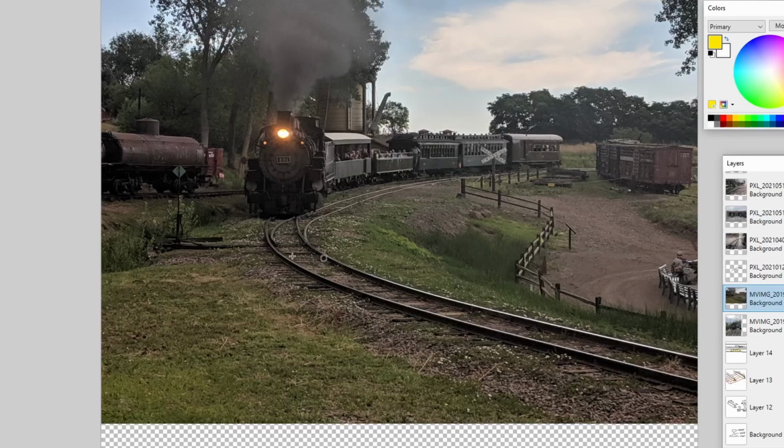Equally important to that is proper grading and proper drainage. Because another problem that we faced here at this location was that the water was kind of pooling and collecting, and wet ground likes to move, and that does not help us run trains. And so we actually installed a French drain all the way down both sides, all the way down the cut, so that all the water would wash down along the side of the railroad, it wouldn't get absorbed into the ground, and then it would drain away from the railroad.